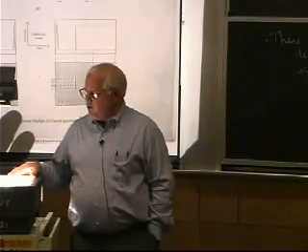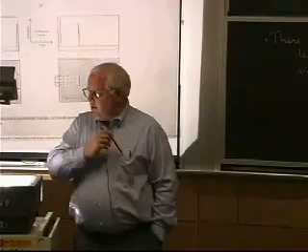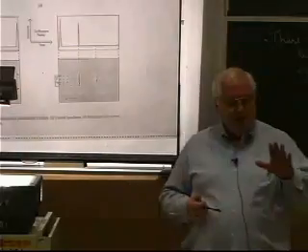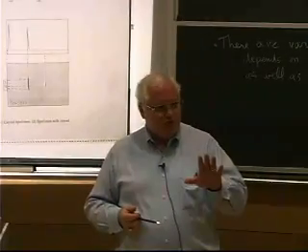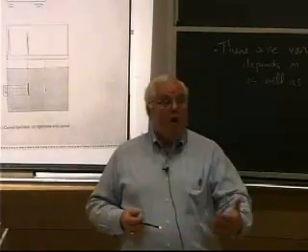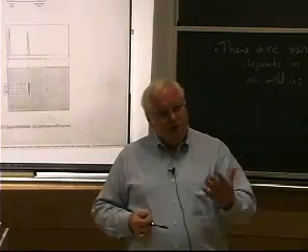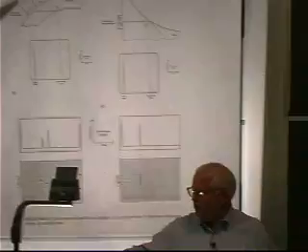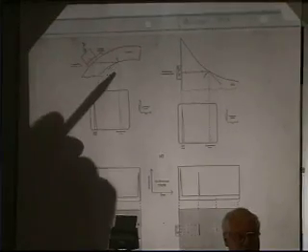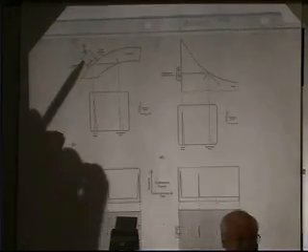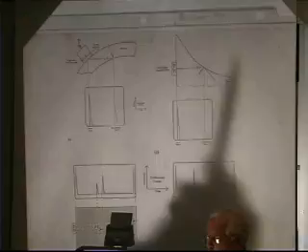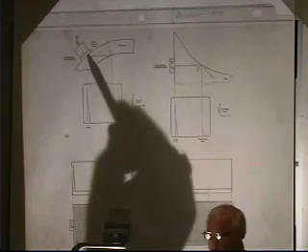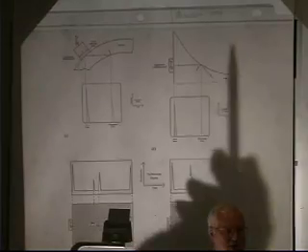It's very, very complex to understand what's really going on, but in the simplest sense, you put a transducer on here. Now, this is a piezoelectric transducer. Typically, piezoelectric is just a material that if you put an electrical input in, you'll get a mechanical vibration out, or if you put a mechanical vibration in, you'll get an electrical output. So it turns out you can use the same transducer as both the output signal, the test signal, and the sensor to detect the wave coming back. Or you can do what they call pitch and catch, where you have one transducer that sends out the sound wave, and then you have another one over here that catches the sound wave.